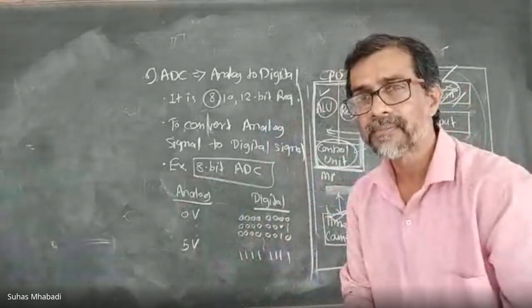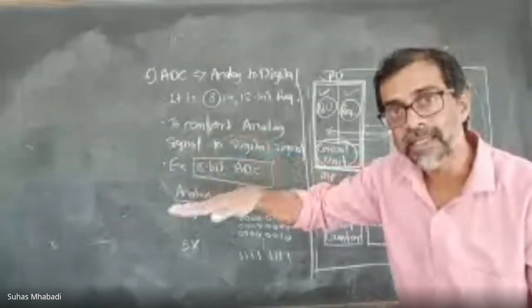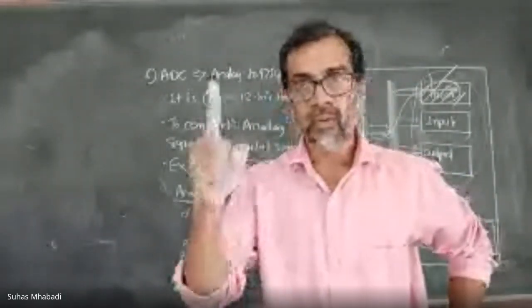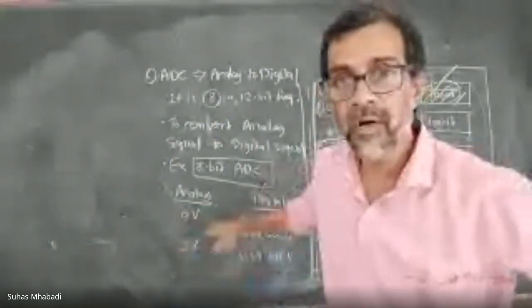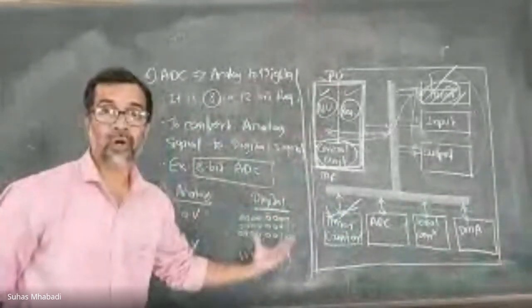Can you tell me? The number of steps starting from all 0 to all 1, how many are there? 8 or 16? Let me help you out. 1 line, 2 steps. 2 lines, 4 steps. 3 lines, 8 steps. If the lines or places are 8, then 2 raised to 8 is 256. Yes, the first will be all 0 and the last all 1.